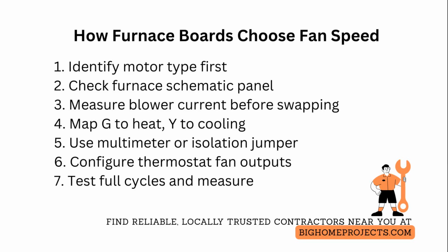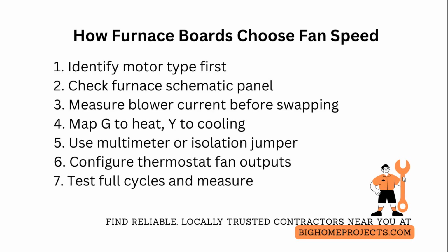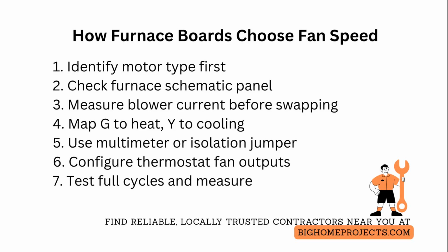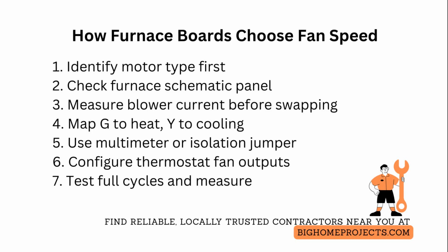Check the furnace schematic on the inside of the access panel for exact tap to CFM values and the control board legend to avoid mismatch. Measure the blower current and motor amp draw with the existing taps before swapping parts so you can select a replacement motor or set the board to match existing load. This prevents overheating and nuisance tripping. Aim to keep motor amperage within 10% of the original nameplate on the same tap.